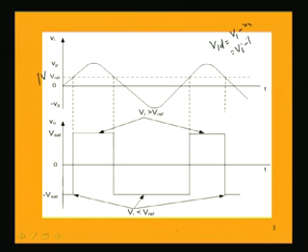So, for this portion it is less. What will happen is that we are finally getting a negative voltage, because Vi is less than 1. For example, if it is 0.5, it will be minus 0.5. So, we are getting a negative difference voltage. So, the output will be negative: A times this VID will be V naught. So, V naught will be A times VID.